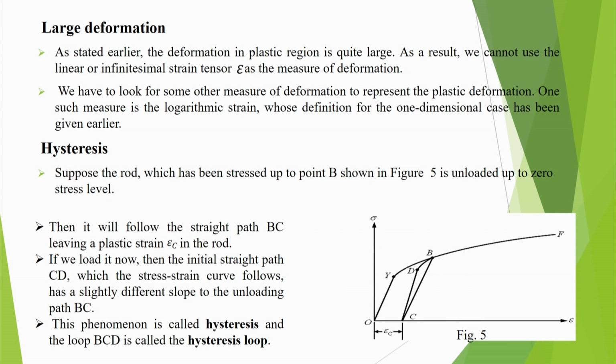Now, large deformation. In machining, we will be dealing with a large amount of deformation. It is not a small deformation. In day to day life, materials also get deformed, but they mostly undergo elastic deformation, and those deformations are very small. I told you that the strains are of the order of 10 to the power minus 3, 1 by 1000. But in the machining process, strains can be very high.